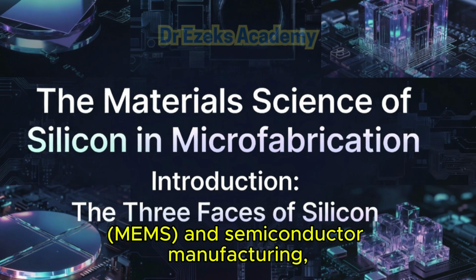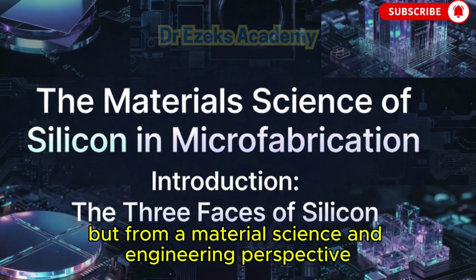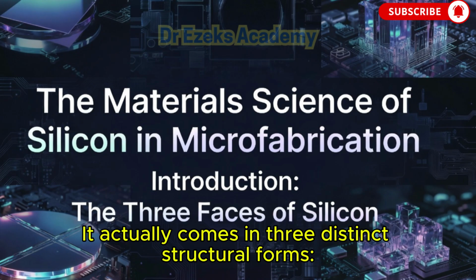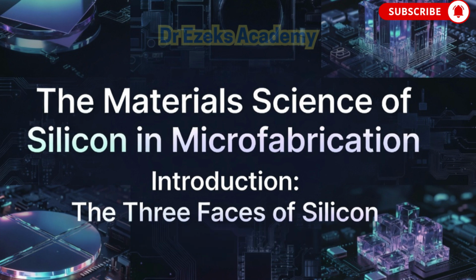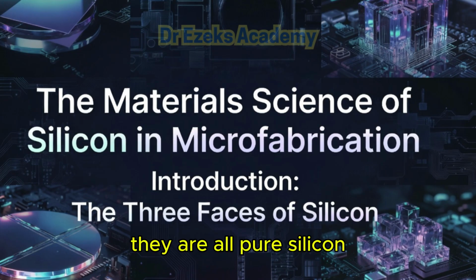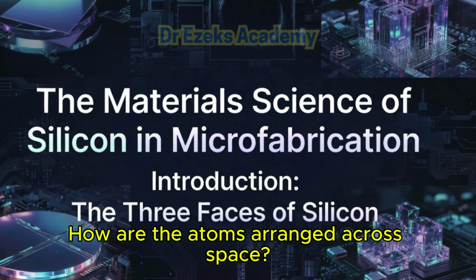When we think of silicon in the context of microfabrication, microelectromechanical systems (MEMS), and semiconductor manufacturing, we often treat it as a singular entity. But from a materials science and engineering perspective, silicon is not just one material. It actually comes in three distinct structural forms: single crystal silicon, polycrystalline silicon, and amorphous silicon. The fundamental difference between these three states lies not in their chemical composition, they are all pure silicon, but in their crystallographic order. How are the atoms arranged across space?